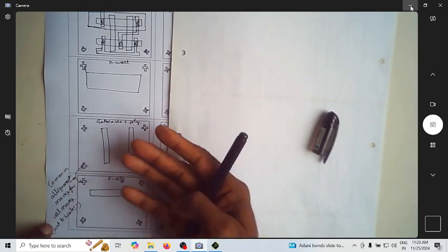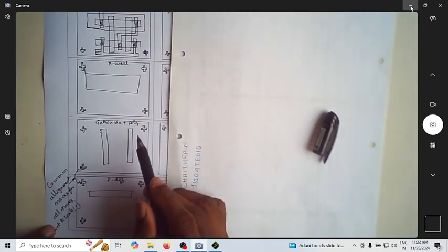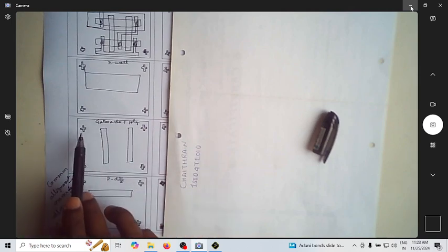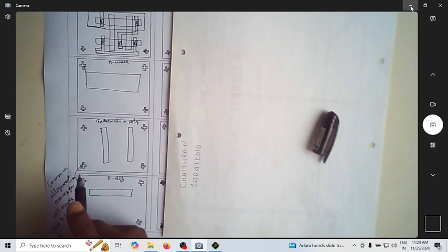Of course, since we are writing it freehand, they are not exactly placed at the same point, but in real time they all have to be at the same point. That's why there are common alignment marks for all masks. Of course, this is not to scale. It should be perfectly to scale when you are actually realizing it.